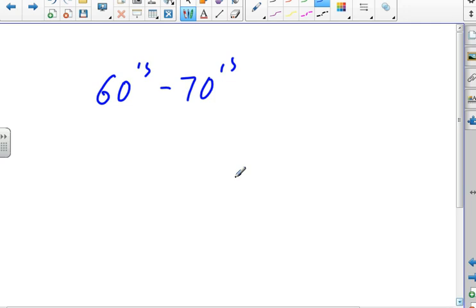On 73, we see that we have relay contacts, but the relay also has auxiliary contacts associated with it. So when you're doing your motor controller and you have the M and you have that 2 and 3 on the side, that's an auxiliary contact for that controller. There are 3 more positions that are empty on that controller. So you could have a total of 4 normally open contacts, or a combination of normally open and normally closed, if you were to buy them and add them to that contactor, or to that motor controller.